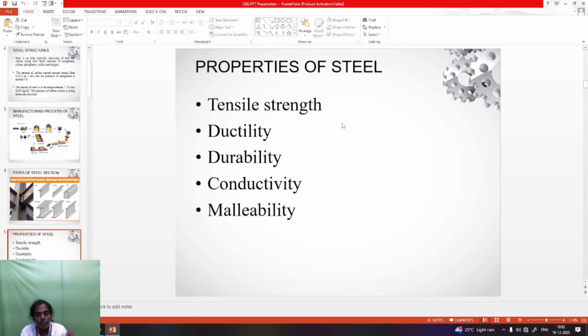Next, bolts are used with the steel member, and bolts have different strengths based on their grade. The bolt grades are 4.6, 4.8, and normally 4.6 is used in our IS 800 2007 code book. In your code book, take the table on page number 18 and read the bolt strength. This is normally 400. Grade 4.6 means the bolt strength is 400 MPa, or 400 Newton per mm square. This is the tensile strength of the steel members. This is an example.